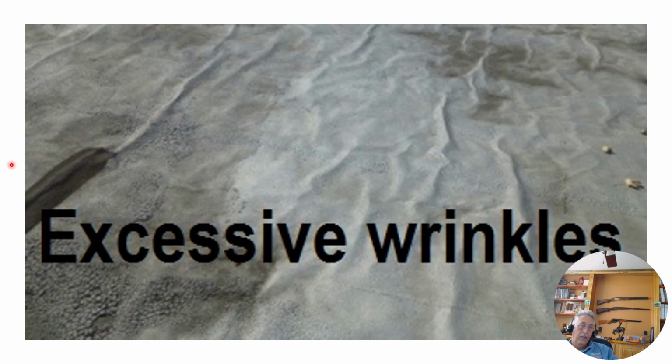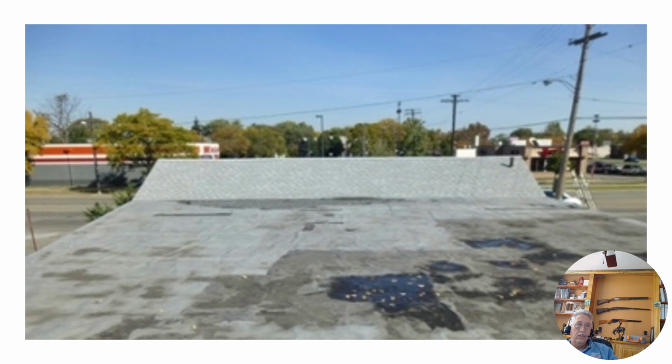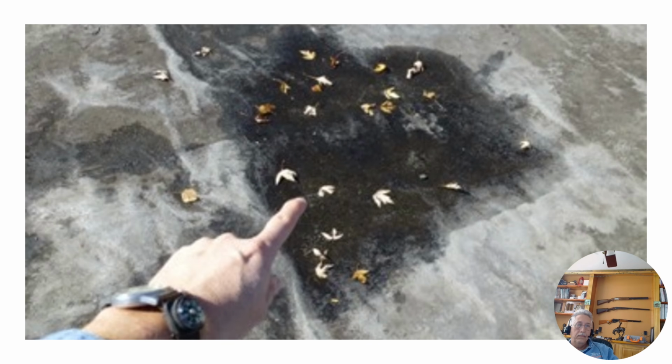So this is surface of structure, this part of the roof, this part of the inspection. Surface of structure, see big sinkholes over here. This whole area is dark. This looks like a problem area over here to me. Give it the finger. So wherever I see something I want to make a comment about in my report, I give it the finger like that. So another deep hole. Again, don't step in those holes. You could fall through if there's rot in there, and there probably is rot. If it's a metal corrugated roof, then it could be rusted out.